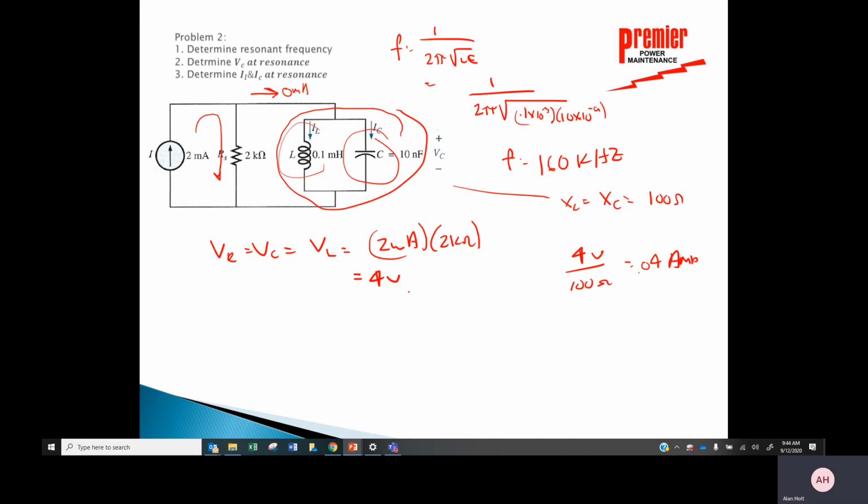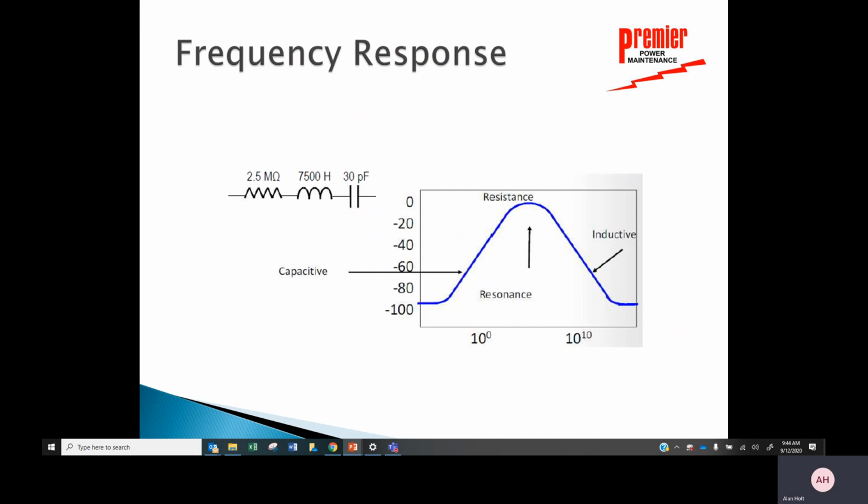But what's happening in this little capacitor-inductor circuit is I've got 0.04 amps circulating in here. It's going this way, and then half the cycle it's going back this way, and I have no current flowing in. So it's an amazing thing, it's called a tank circuit. It just dies right there. But there is current flowing back and forth between those two components. The sum of those two currents is basically zero, as long as it's pure capacitance and pure inductance.